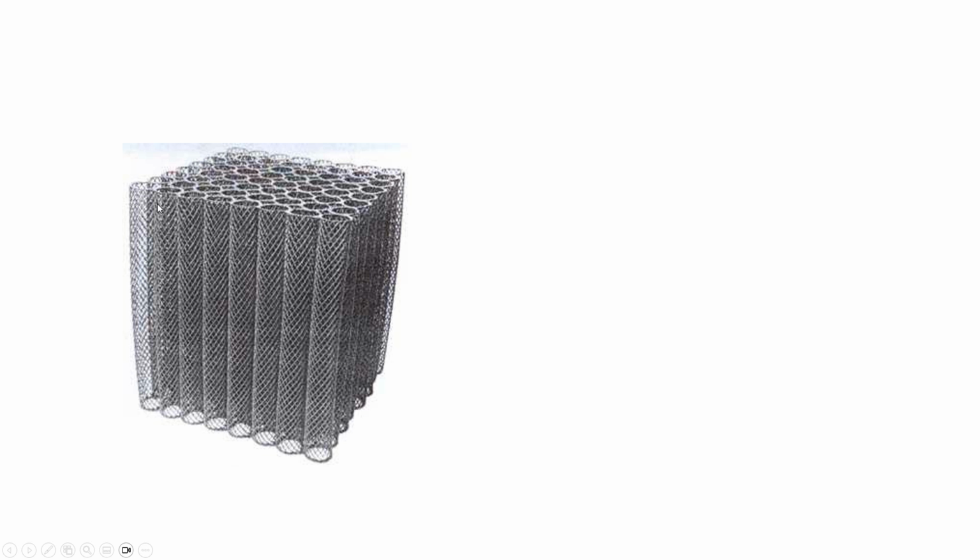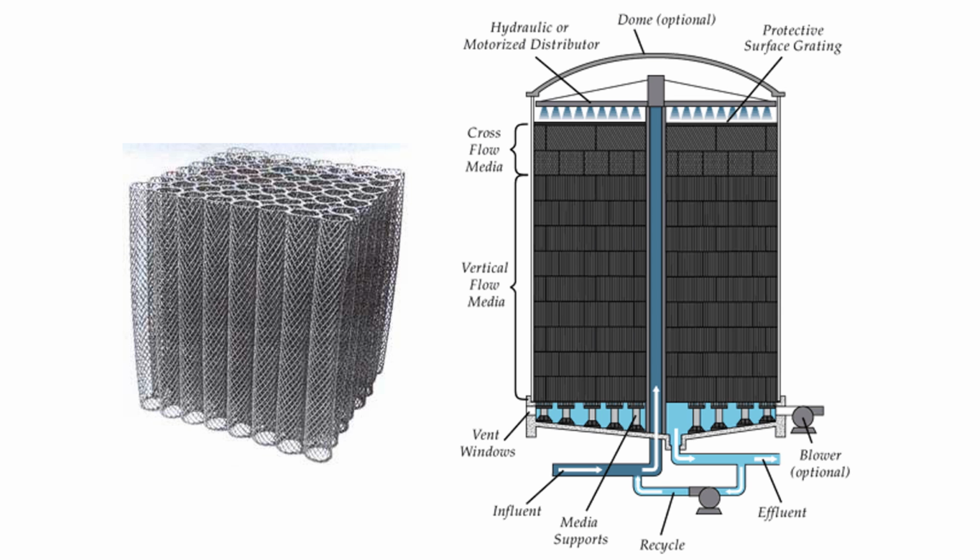Here's another possibility: you just drop a more solid mesh frame into the trickling filter. Some installations have had hanging sheets of plastic that they spray the water at the top and they inject air at the bottom. And as long as the air can circulate around inside of the filter, then the bacteria are happy because they have the oxygen that they need, they have the water that keeps them wet, and they have the BOD in the water.